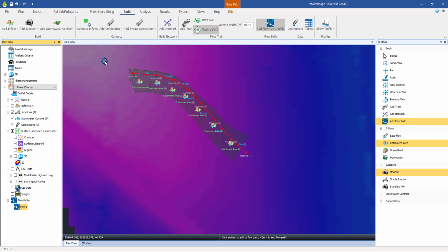There's then the second stage, or the second criteria, that these pipes must fulfill. And that criteria is a no flood criteria. So that's during a higher return period storm, typically a 1 in 30 year storm. We are meant to design the pipes such that they don't flood. Now this is a dynamic simulation.